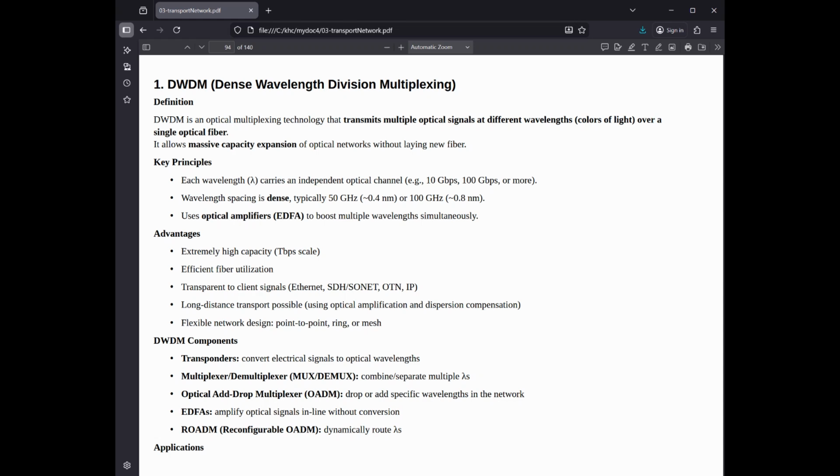Summary comparison. Feature: DWDM spacing; EDFA role: keeping signals strong over long distances. Primary goal: maximizing the lanes in a fiber. Standard: ITU G.694.1, 100 GHz/50 GHz. Operates in C-band and L-band. Key benefit: high capacity, terabits per fiber; multi-channel amplification, low cost per bit.